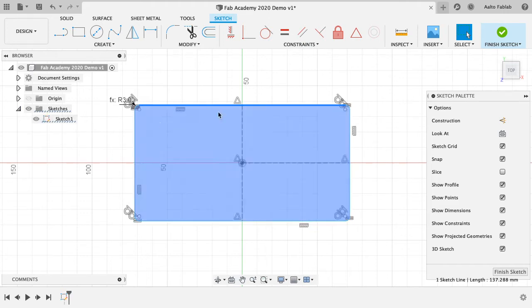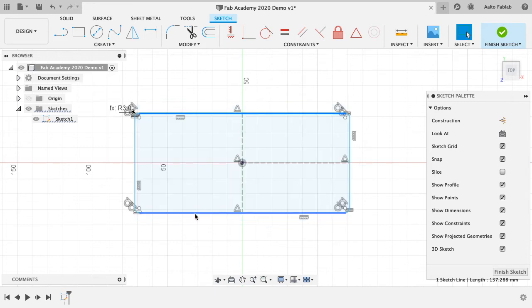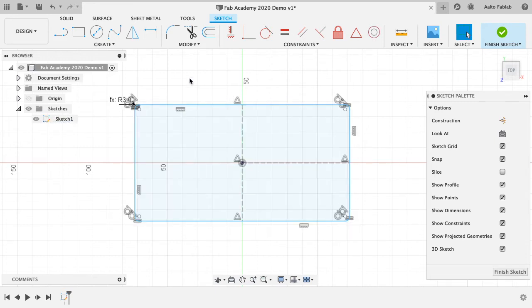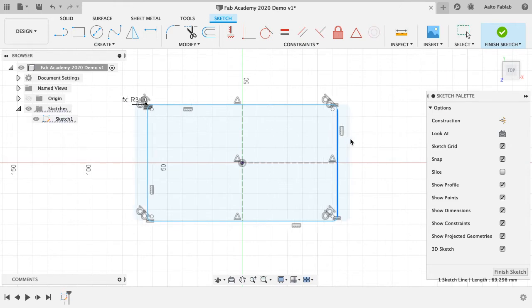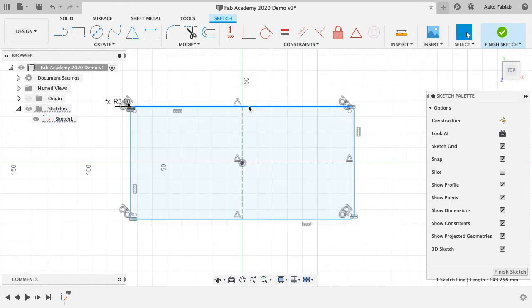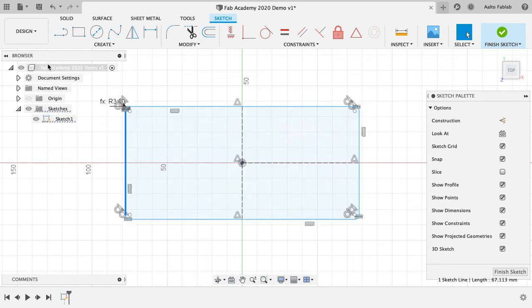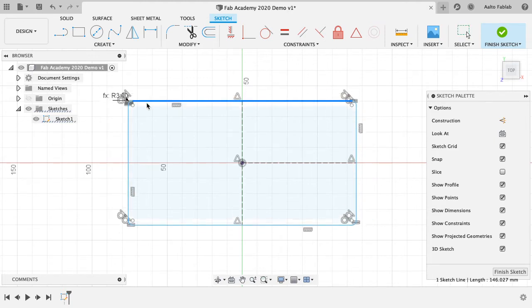And then another important concept in these kinds of CAD sketches is that you should always aim for constraining the object as much as possible. In Fusion you can tell that the sketch is constrained if a lock icon appears here in the project browser. At this point it's not there, because you can still freely move it.